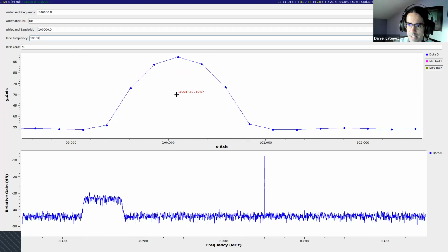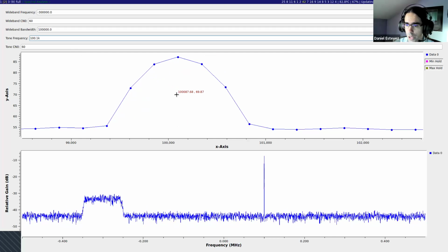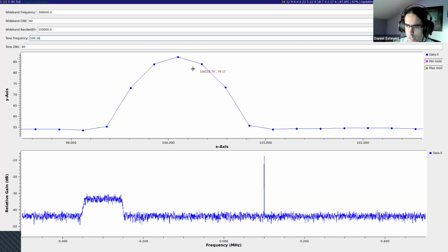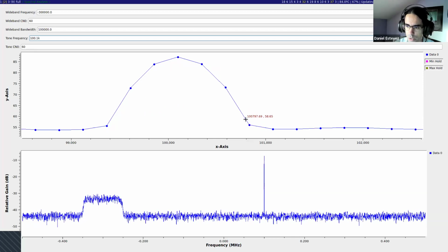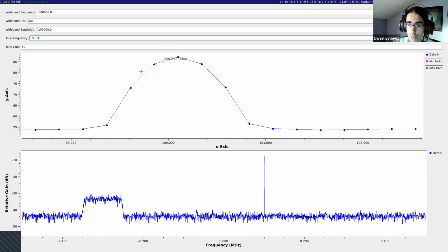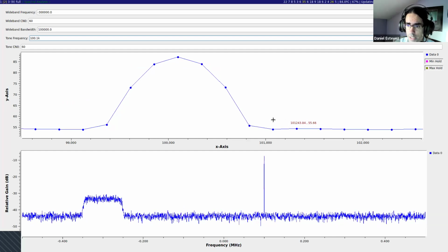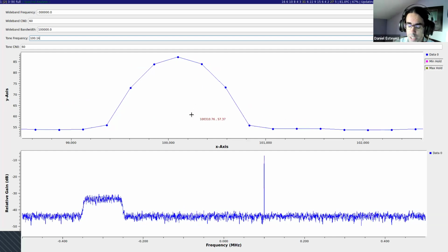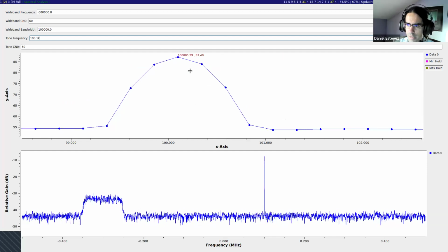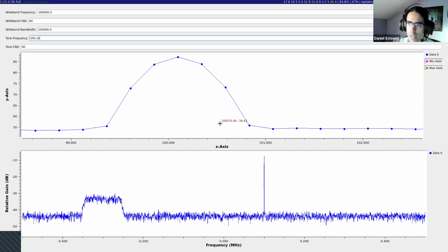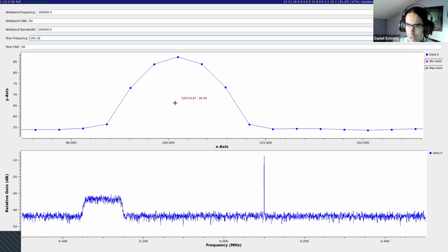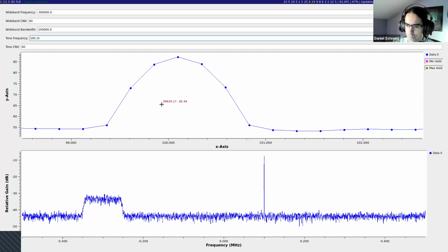It's like designing an ideal filter. It's impossible. So we have to live with some leakage in the shape of this signal, and that is also determined by the FFT window. There are windows which have wider leakage, and there are windows with narrower leakage. And usually we cannot optimize for both scalloping losses and for this leakage. If we choose to optimize one of them, we lose on the other one. That's how these problems usually behave.